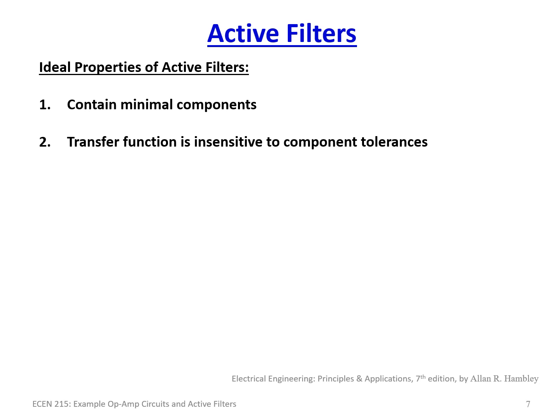As you've learned in the labs, there's tolerance to resistors. When you buy a resistor that's 10 kiloohms, it's 10 kiloohms plus or minus 5%, or it's plus or minus 1%. Of course, as you want a tighter tolerance part, the cost of the part goes up. So you can get down to like 0.01%. You can get a really accurate resistor, but you're going to pay for it. So you want to try to make sure that the transfer function of your filter is insensitive to those minor changes in tolerances on the components.